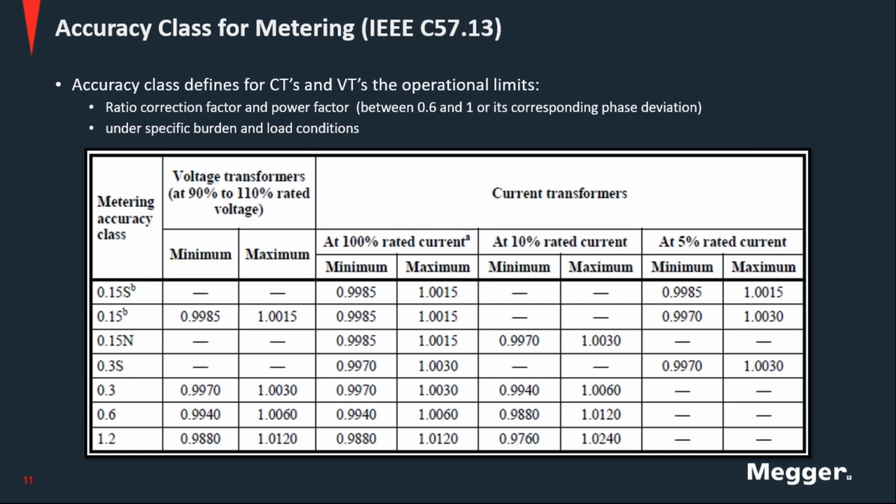So you have relays, you have coils, you have meters connected to these transformers, and well, it is providing signals, voltage or current, but of course it needs to provide some power to these elements. So the loading conditions must not exceed certain limits.